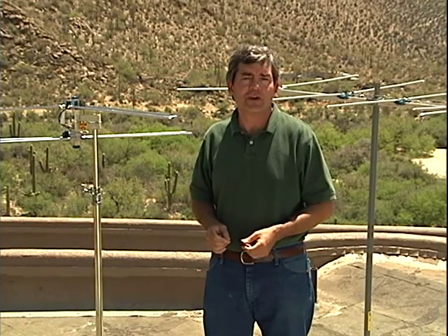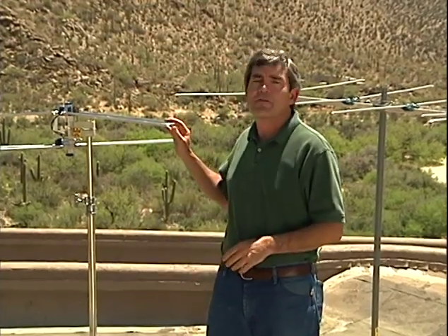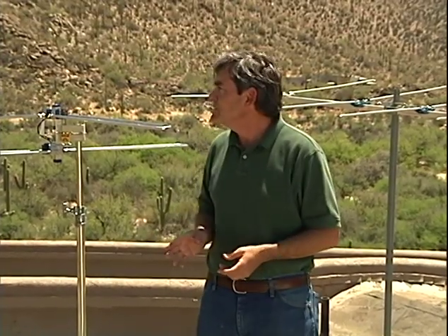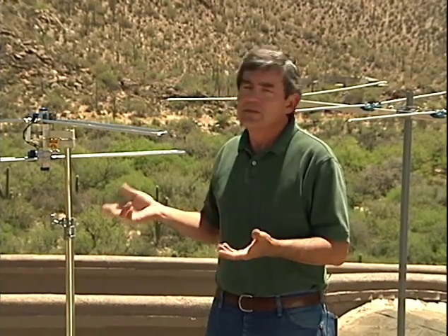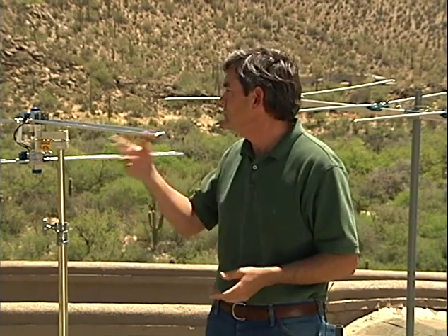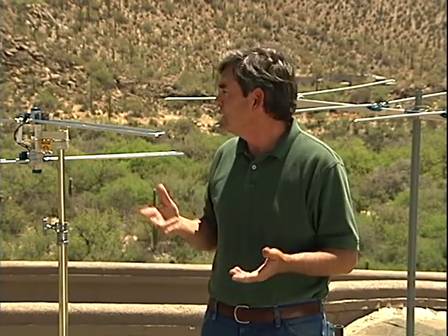While broadband VHF antennas can certainly receive FM signals, using a separate outdoor FM antenna is a good idea for a couple of reasons. First, FM stations tend to be scattered geographically over a wide area, rather than clustered together like TV stations. And secondly, high gain's usually not necessary for FM stations in a 40-mile radius, and using a highly directive TV antenna may actually be a disadvantage. And FM signals are not nearly as susceptible to multipath interference as TV signals are.